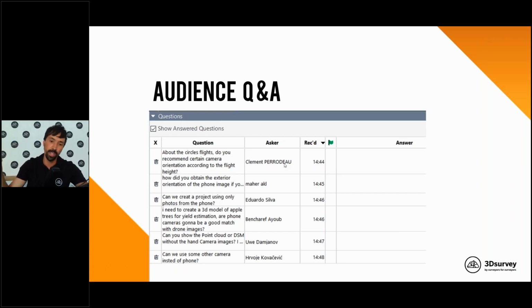You actually put a SIM card into the drone RC, which directly connects to the network and gets the corrections. So this is through RTK, and in a second you get all the RTK coordinates. So it's really convenient. We don't need to buy an additional stick for RTK and use it as a base and then do the post-processing for RTK coordinates. This is available in all countries that have a network of GPS stations. If you don't have this network, then you need to use the additional stick for the RTK.